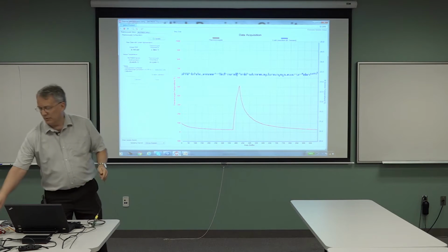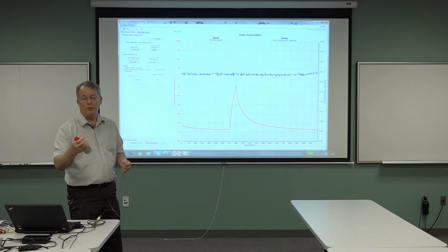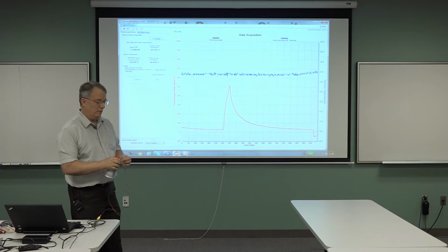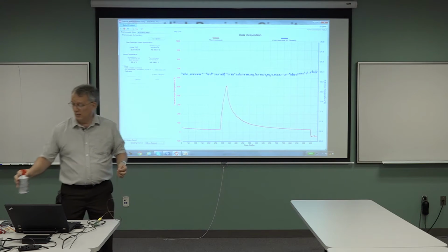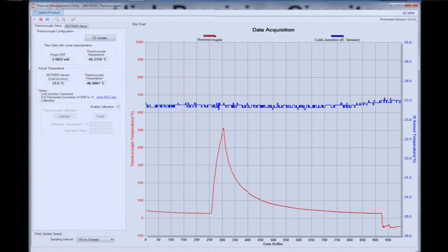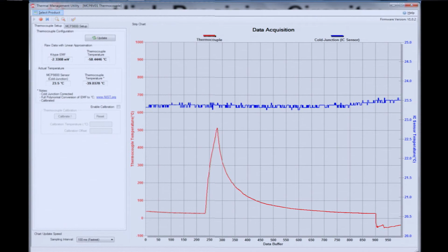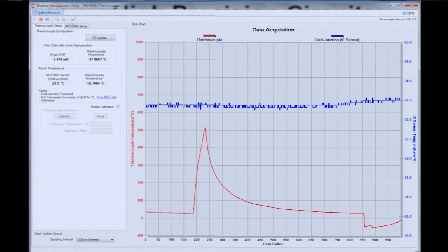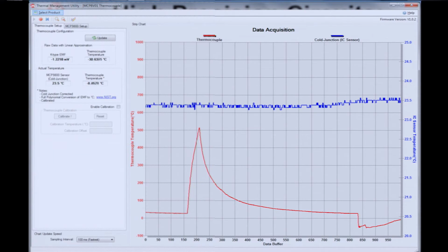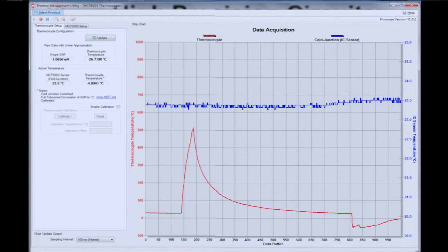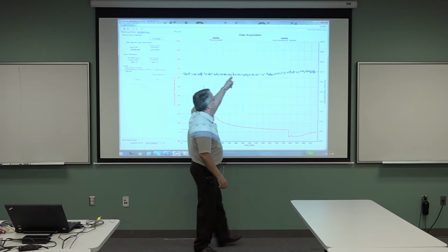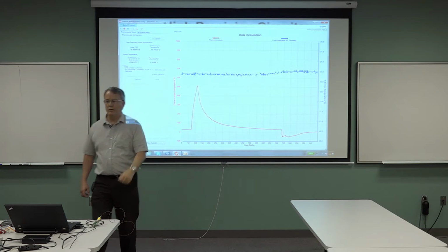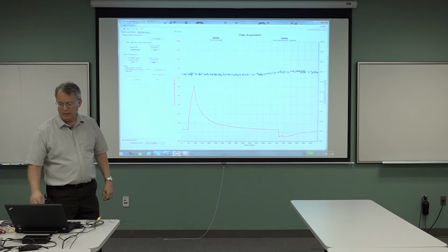The other thing I can do is I can get out this freeze spray can and make it go cold. More than that. How about that? So it went down to, I'm estimating, minus 50 degrees C at this end. So everything works out nice. Theory matches reality. But there are a couple of anomalies, right? The anomaly of why this temperature goes up after I hit it with heat on the end. We've explained that. But why does it take so long to decay?